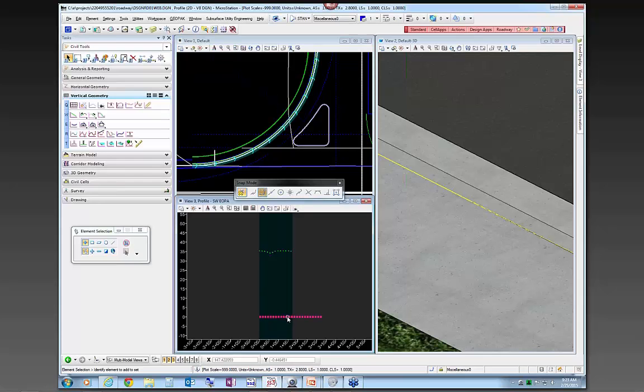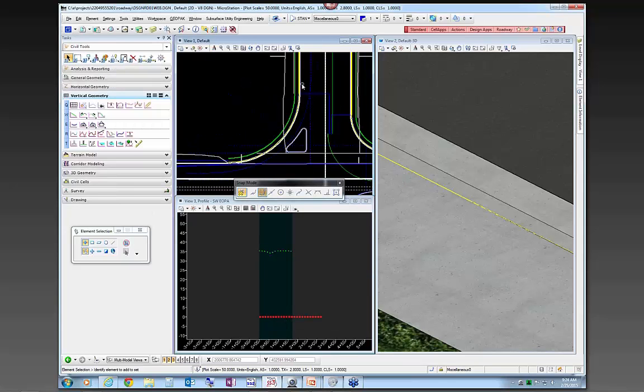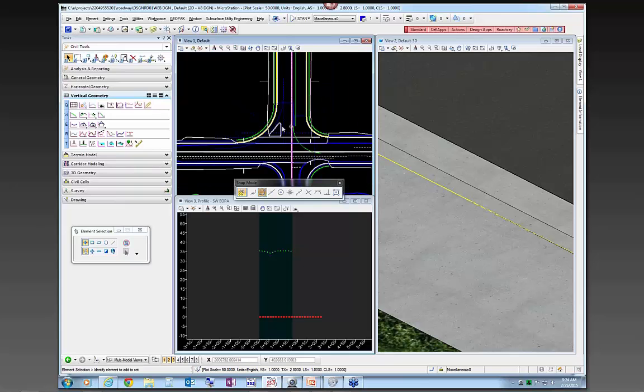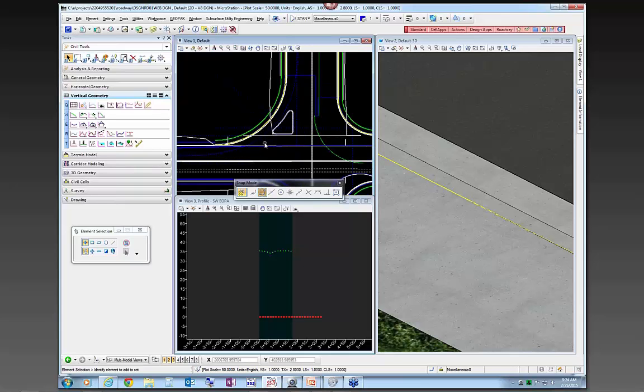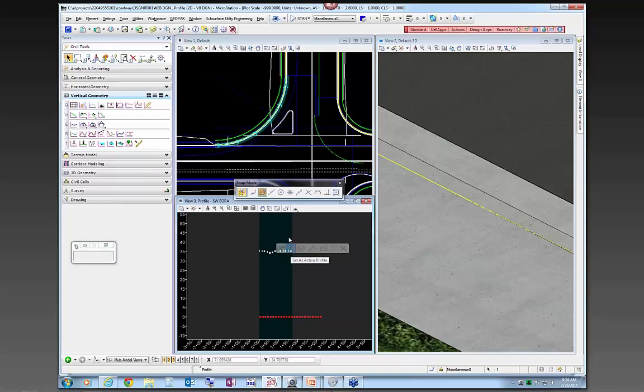So what you can do is, and this will automatically become active even though it's in error, it sometimes works real simple, but I think because of some of the trim backs in this data set, it's not working. So there's a backup plan for it. What you can do is just set this as the existing ground, set it as active for the time being, and I'm going to show another method of doing this.